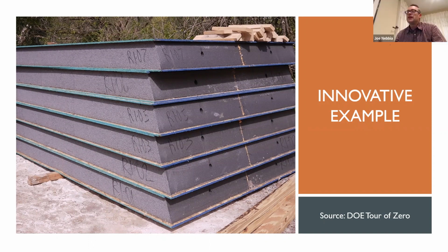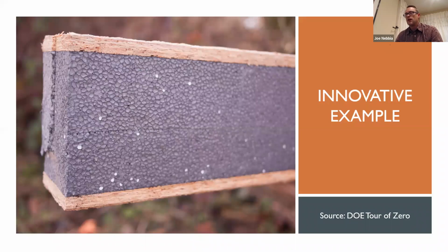Yeah. So in that case, you can comply with any of the 0 plus 13 or 0 plus 20 or whatever the continuous only insulation is, or you can use the U value to demonstrate, because it's not interrupted by framing, that this is meeting the U value in the code. It's another example of a SIP there. I think that might be the spline at the roof, but I'm not totally positive about that.